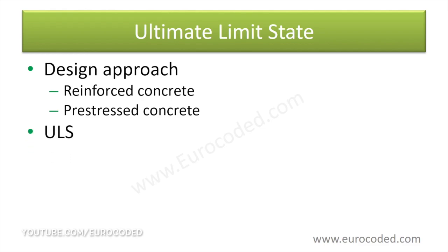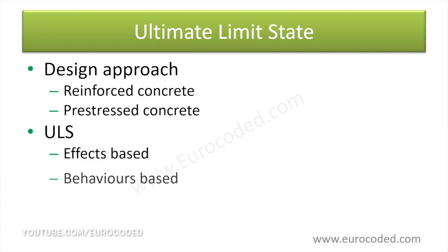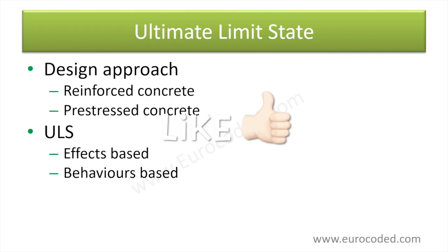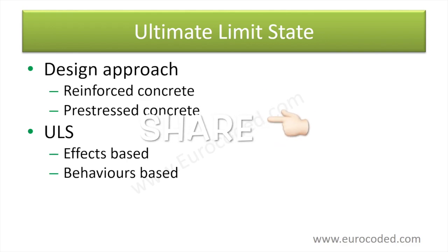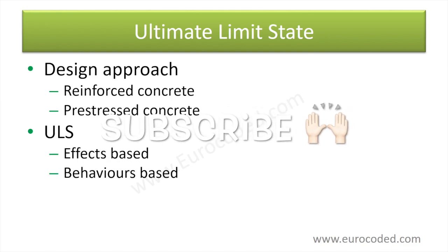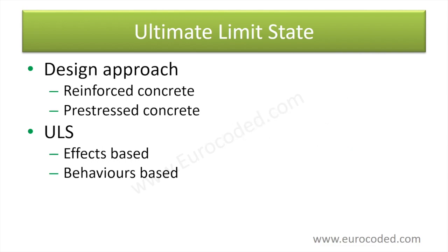The ULS design approach is based on effects and behaviors rather than element type such as beams or columns. Effectively, it doesn't matter what type of element it is, rather what the element is subjected to, as an example, bending, shear or torsion. However, when it comes to detailing, there are specific clauses to cover different types of elements.